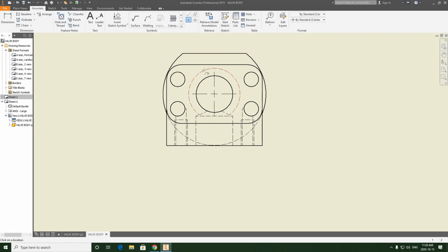And this hidden circle is drilled out by this front drill, so we're not going to place the center line to the larger one, only the smaller one that's whole, right? We don't apply center lines to circles that are not fully 360 degrees in circumference. We're going to do these ones.